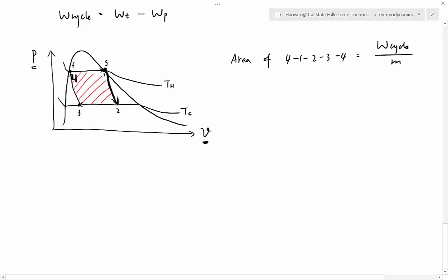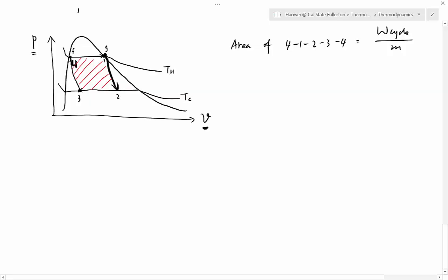And again, if you have a power plant, we want to know what the efficiency is. Efficiency again is eta and is defined as purpose over cost. Purpose again is W cycle, the net amount of electricity you can output. The cost is QH. You burn the gas, you release QH. And then just like before, W cycle can be rewritten as QH minus QC, divided by QH.